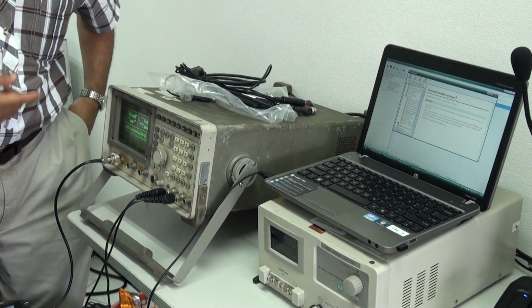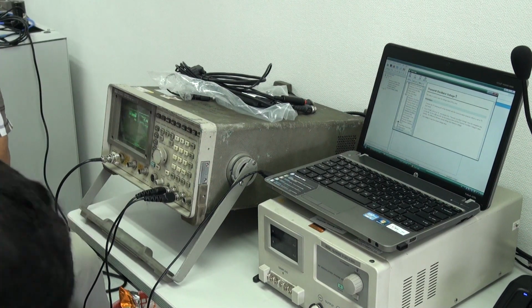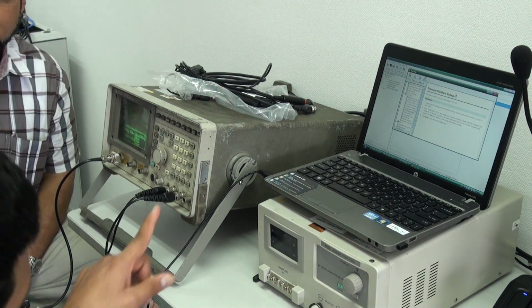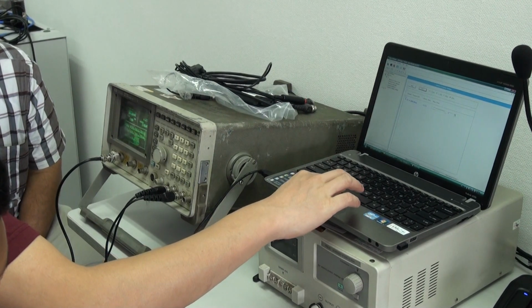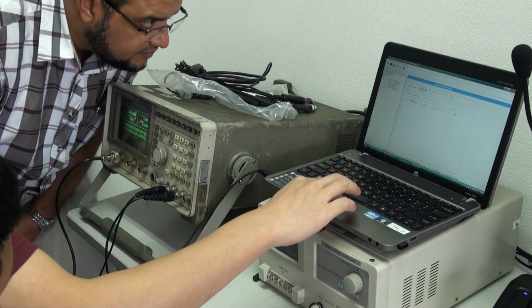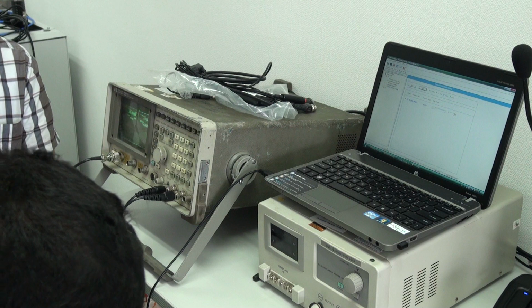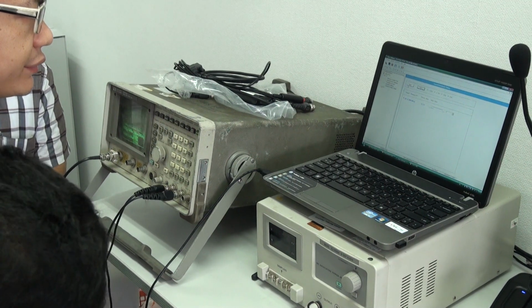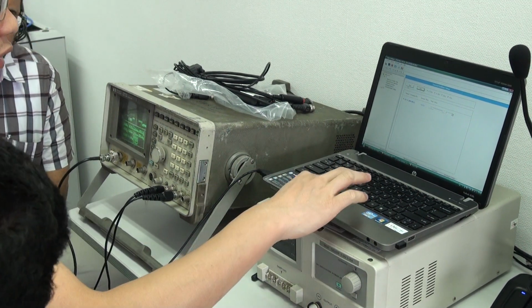Yes, sir. PL lock, which is phase lock loop, locks the frequency to make sure you transmit at what it should be all the time. So always, in fact, you just need to read and then save. Already by default it is there in the firmware. After retuning, we have to save. No, read and save. That's all, read and save.